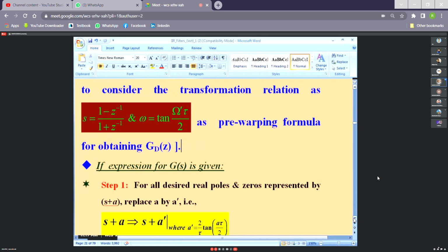They are expected to be the same as the analog filter critical frequencies. How are the analog filter critical frequencies obtained? From the location of the poles and zeros. Recall your knowledge of Bode plot. They are the breakpoints.